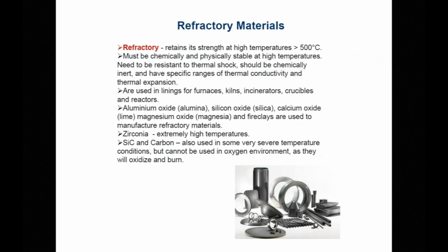Refractory means it retains its strength at high temperatures, say greater than 500 degrees C. It must be chemically and physically stable at high temperatures, need to be resistant for thermal shock, should be chemically inert, and have specific ranges of thermal conductivity and thermal expansion. That is why a very common use of refractory ceramic materials are linings for furnaces, kilns, incinerators, crucibles, reactors.